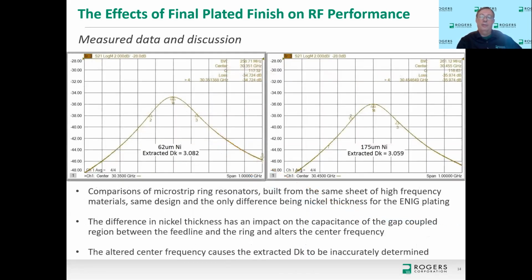And then one other comment I want to make about final plated finishes that I run into a pretty good amount is test methods. We have a lot of customers that will do evaluation on our materials, and one of the more common ones is using a microstrip ring resonator. Those are thought to be pretty good test vehicles for a lot of different reasons. And that's true at lower frequency, but when you get to millimeter wave frequencies, the microstrip ring resonators have a lot of variables that really need to be considered. And I've got another entire presentation on that if anyone is interested.